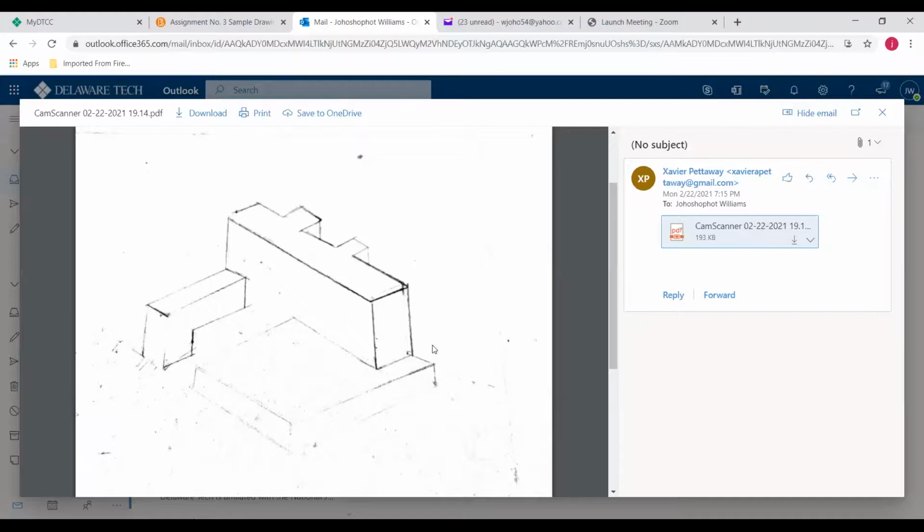Okay, yeah. You've got to use your T-square, and you've got to keep that T-square tight against the straight edge of your drawing surface. If you don't do that, your lines are not going to be vertical. So just make sure that you're keeping that T-square tight against the edge of your drawing surface. This is the right dimension, but the line is not straight. It should be 90 degrees, okay? Good. Yeah, I'm going over them.